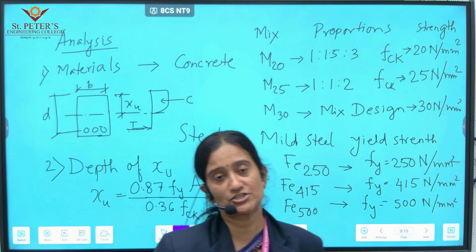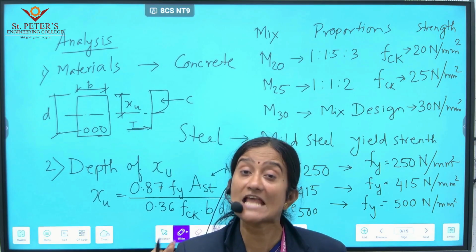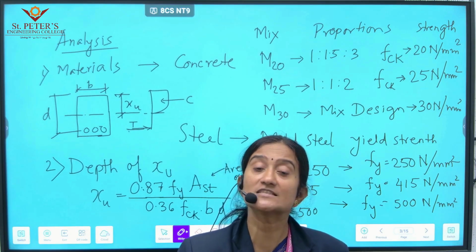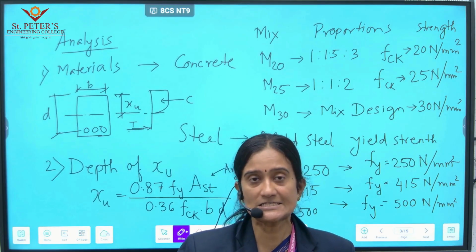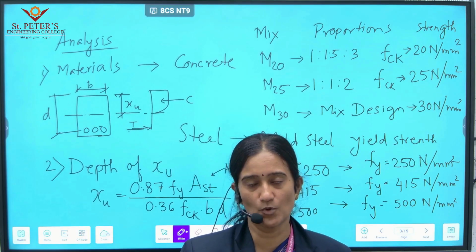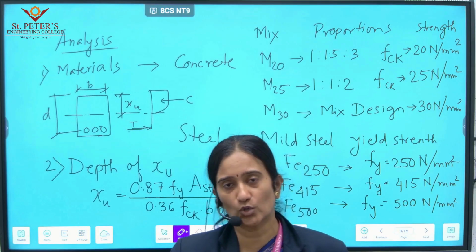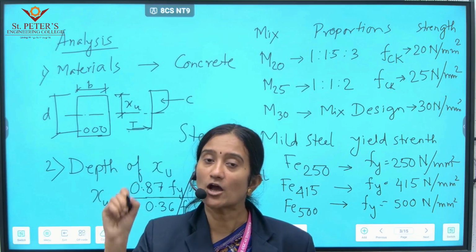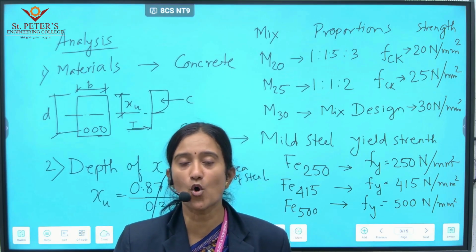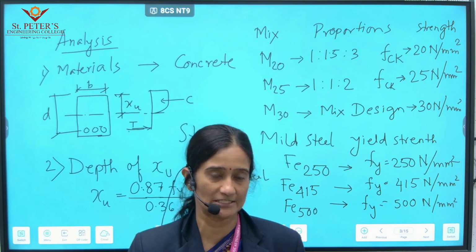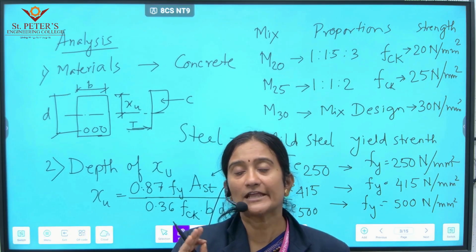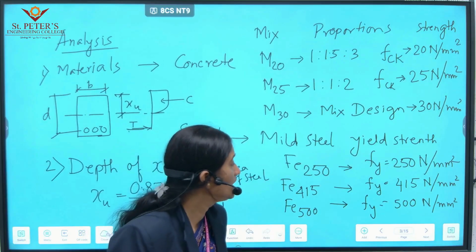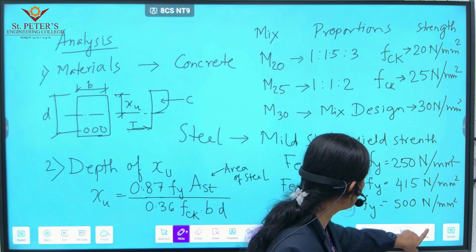In an under reinforced section, the compressive strength is less than the tensile strength. But this structure is okay because the tensile strength is more, so it can take extra load also. But when we go to an over reinforced section, the compression strength C is more than T, and it leads to the failure of the structure. The compression fails.